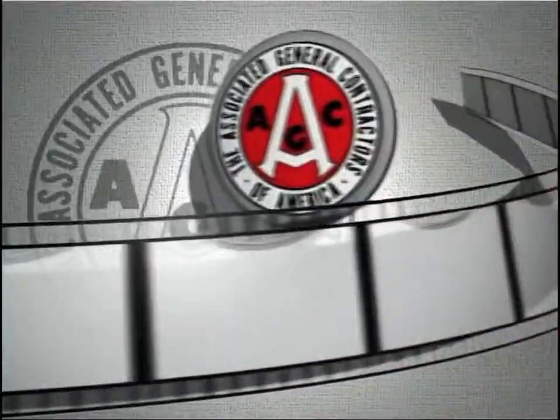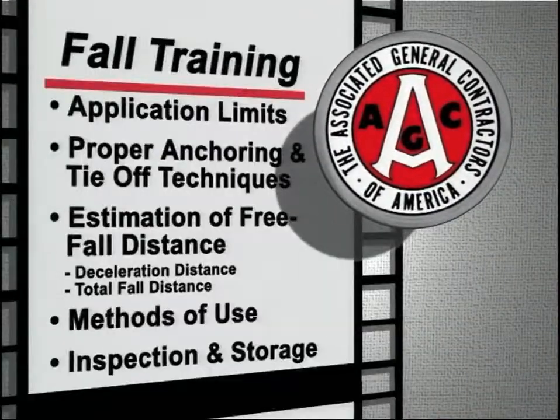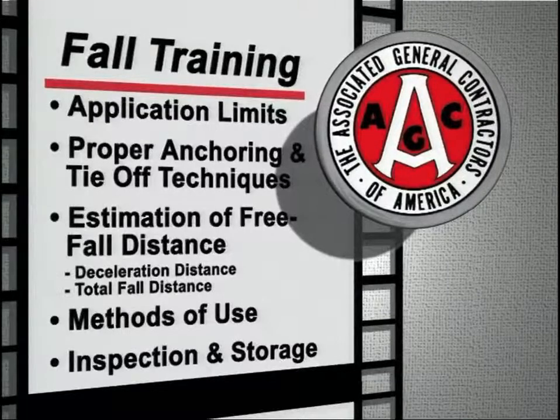This training should include application limits, proper anchoring and tie-off techniques, estimation of free fall distance, including determination of deceleration distance, and total fall distance to prevent striking a lower level, methods of use, and inspection and storage of the system.